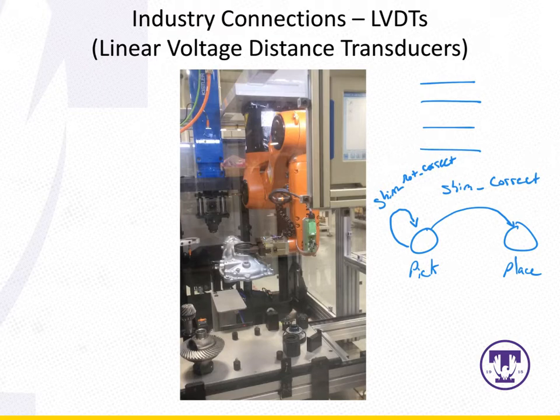So it's sort of like a hammer and a screwdriver. You have different tools in a programming toolbox, different approaches to solving a problem. When you have a linear sequence of events that you need to happen in that specific order, the bit latch sequence is a great way to go about it. But when you have a set of things that need to be done, but it's based on the state and environmental conditions, then a state machine is a better approach. So with that being said, we're going to dive into how state machines work and how to approach programming them.